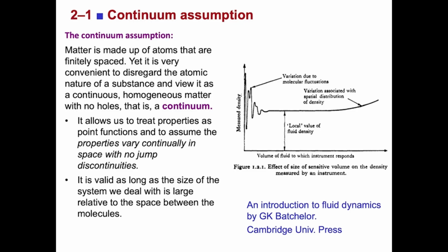When you talk about the continuum assumption, it is essentially saying that any property or parameter associated with a material, let's say its density or its mass, the yield strength, the velocity, the forces or stress distribution, any property or parameter that is associated with a material, you're assuming it to be continuous.